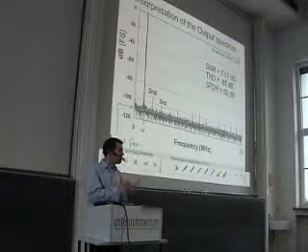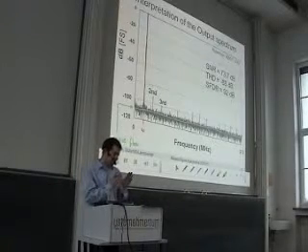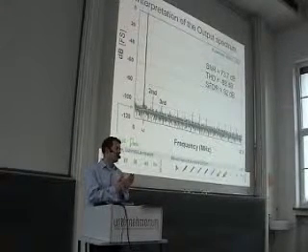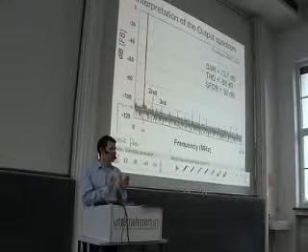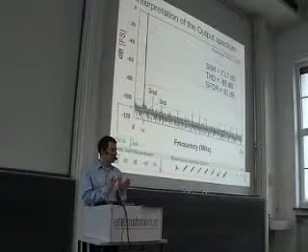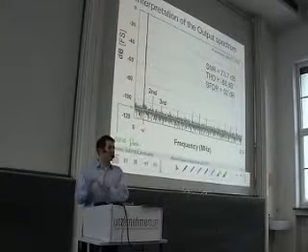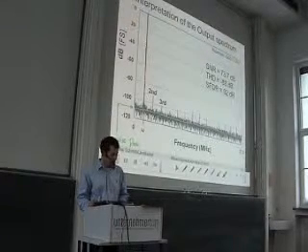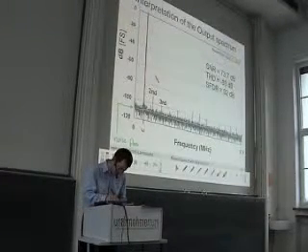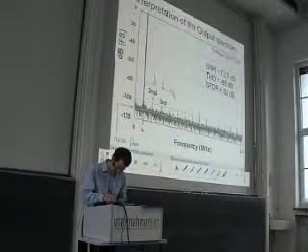You know, non-linear distortion means that even if we have an ideal sine at the input of the nonlinear system, at the output we get a signal that contains components with twice, 3 times, 4 times, 5 times the fundamental frequency. And these are the so-called harmonics. So these are the harmonics that lead to the distortion.